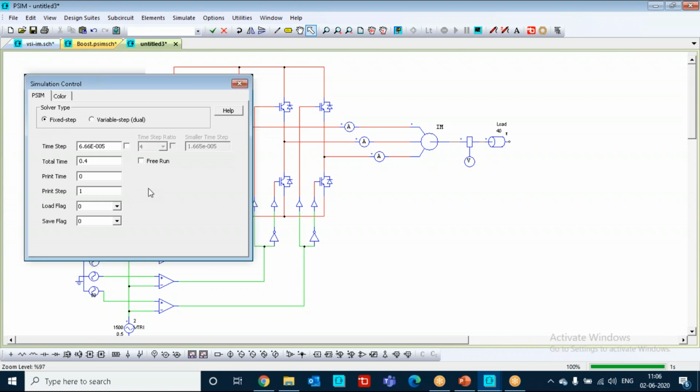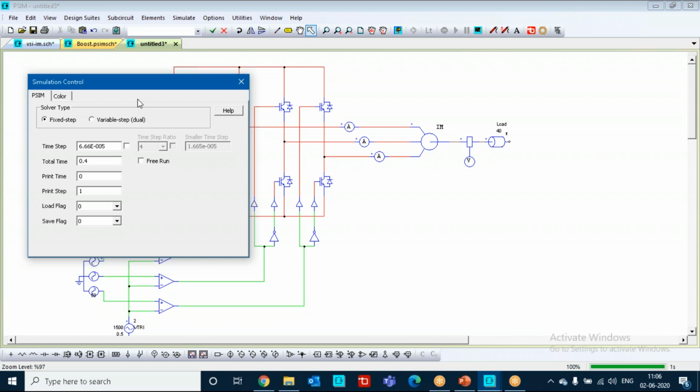One important aspect is that time step selection should always be based upon your frequency component. What is the highest frequency component? You have to select according to that. A typical suggestion is that the time step times your frequency should be less than or equal to 5 to 10%. That will be around 25 to 50 microseconds for a transient of, for example, 2 kHz frequency.